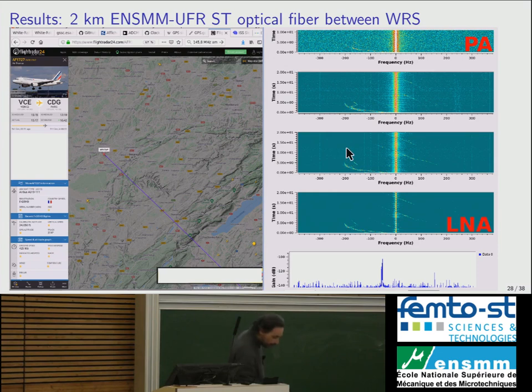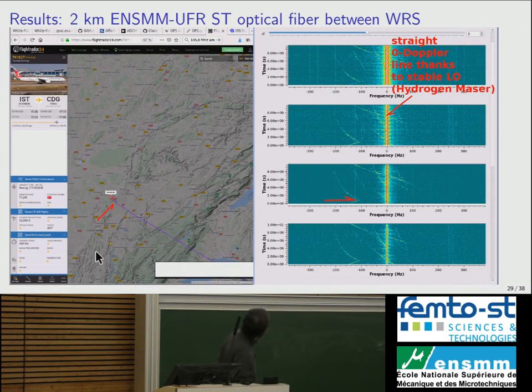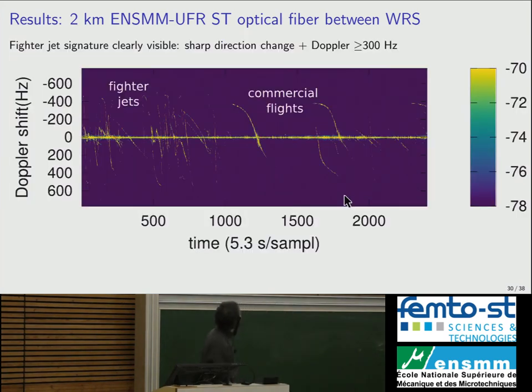So here's a plane flying a few kilometers from Besançon, and this is what you detect over here. As this plane has been turning along its path, you see here that the plane has turned, and that's the projection of the velocity vector towards your antenna array. So obviously you detect the speed of the plane flying overhead. If you do this with fighter planes, they will have an obvious signature. This is a commercial flight with a nice linear path which looks like an arctangent as you project the velocity.